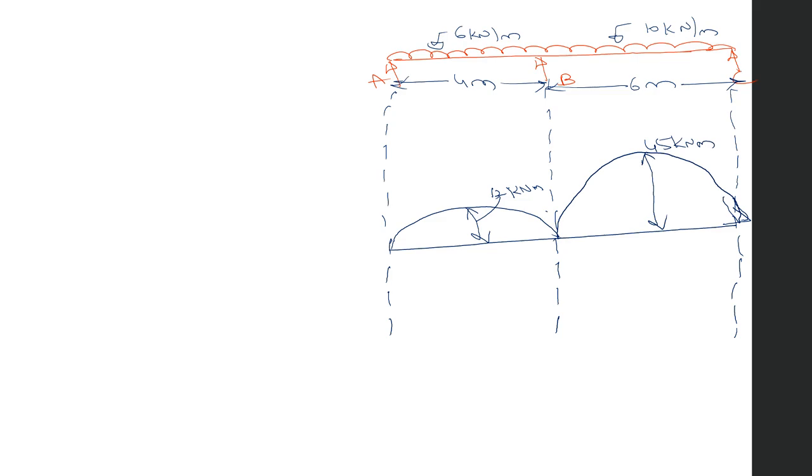But for calculating the fixing moments at the support B, we know that in equation 1 the unknown terms are A1 x1 bar and A2 x2 bar. Here A1 is nothing but the area of the bending moment diagram due to UDL on AB. So it depends upon the area of the bending moment diagram due to UDL. This is the shape of a parabola.